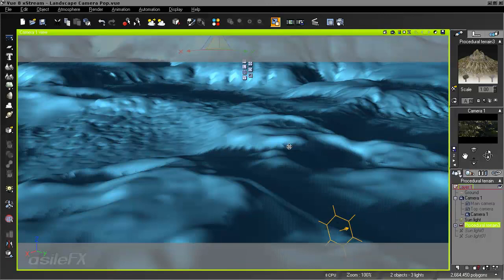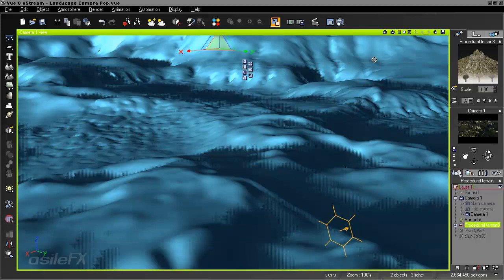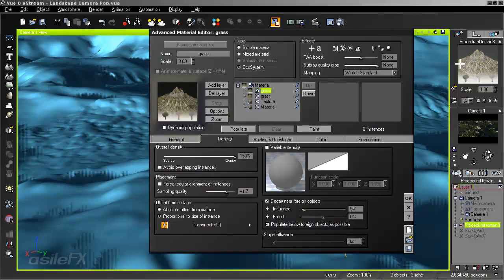But when I save the file, I don't want to have a direct population within the scene unless I've painted or customized any area of it. Anytime the scene is populated, it's going to massively increase the file size. So if you're using dynamic population, that's not typically an issue because that's cleared out before the scene is saved, and that's not going to be part of the file.